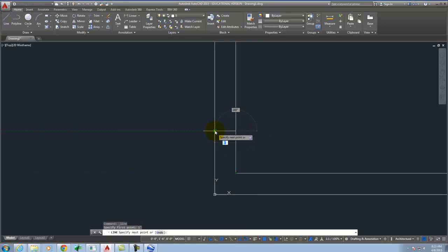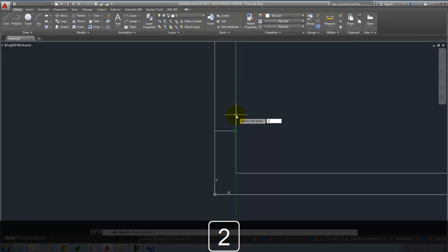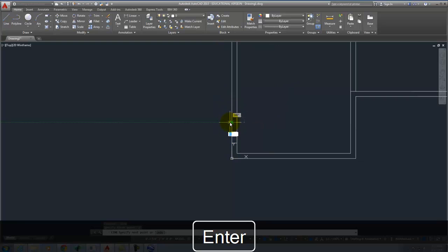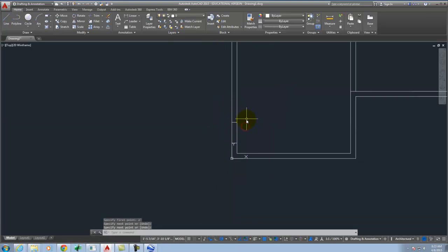Okay, so it takes a little bit of practice to get used to how this works, but it's a real fast way of being able to draw referencing other points without having to do any math. So for example, if I wanted this to be 2 feet away, previously we did an offset, right? I could do the same thing though by setting a point there, dragging up, and again I haven't clicked it in at all yet, and I'm going to type in 2 feet and specify that that's my next line. Okay, so that is this snapping, show snapping reference lines is on.